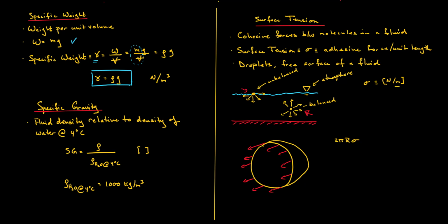Okay, so we have a radius of r, and so this free body diagram would also require us to show a pressure acting on this half of the droplet. So we can write here a pressure. We could define it as delta P. So a pressure is a force per unit area, so we need to multiply it by the area, which would be pi r squared.